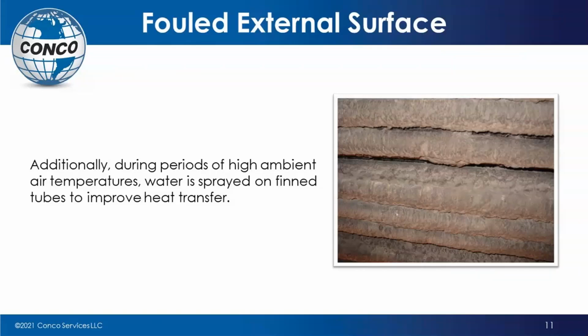But whatever's in that water now begins to break down and solidify itself to the fins. So what happens is you end up with something looking like this, where you have a heavier fouling now on the tubes themselves that you've got to get off and remove if you want any kind of efficiency in your unit at all. Many times now you're beginning to derate when you get to this point.